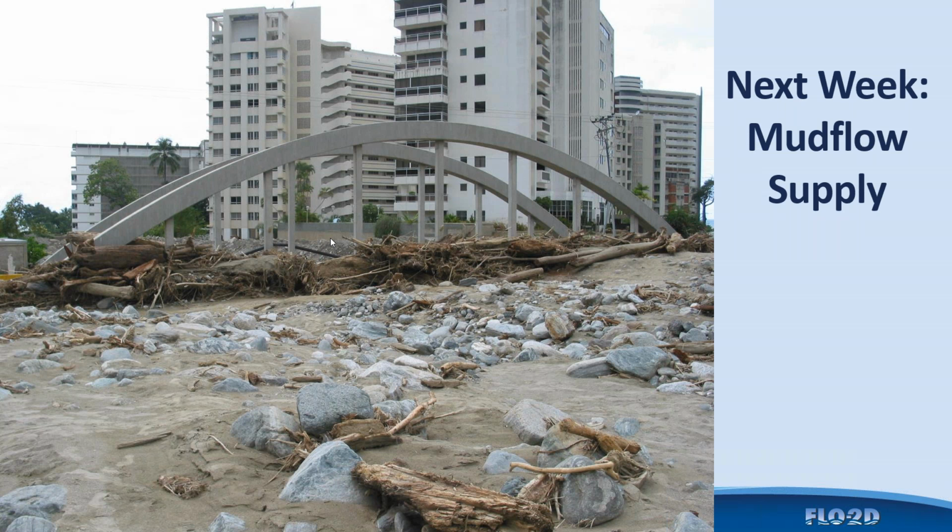In the papers that I wrote and in my PhD dissertation, I give the clay concentration, some plastic index values, and all the data that you would have normally with that. If you have that data associated with another event and you pay for getting the hydrometer analysis and doing the plastic and the Atterberg limits and so forth, yes, you could compare that with other published data and make a reasonable, educated selection of the sediment concentration by volume.